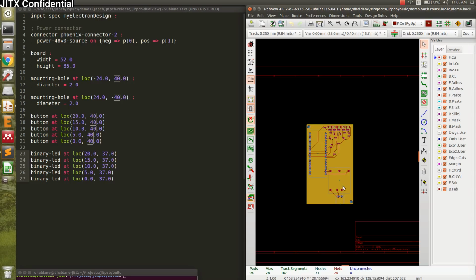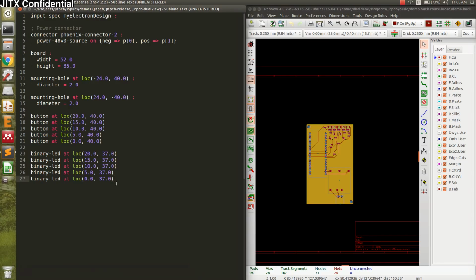So that's a good start, but now I have a sensing board without any sensors on it. So I want to sense sound, so I'll add a microphone. I want to sense vibration, so I'll use an accelerometer. Or 2, why not? And I also have an off-board temperature sensor I want to use, so I need to power it off of 3.3 volts, and it has a UART interface. So I'll use a connector. And it'll be the same screw terminal family, but a 4-pin version.